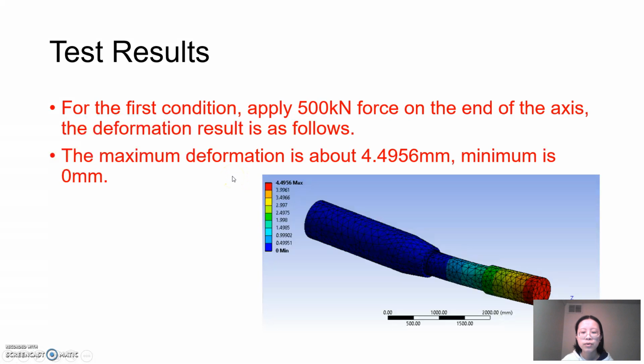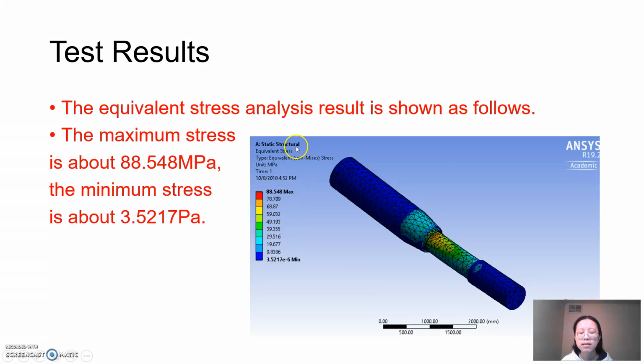This is the test result. For the first condition, I applied the force only, and the deformation result is shown like this. The maximum deformation is about 4.5 millimeters, and the minimum is 0. This is the equivalent stress analysis result. The maximum stress is about 88 MPa. The minimum stress is about 3 pascal.